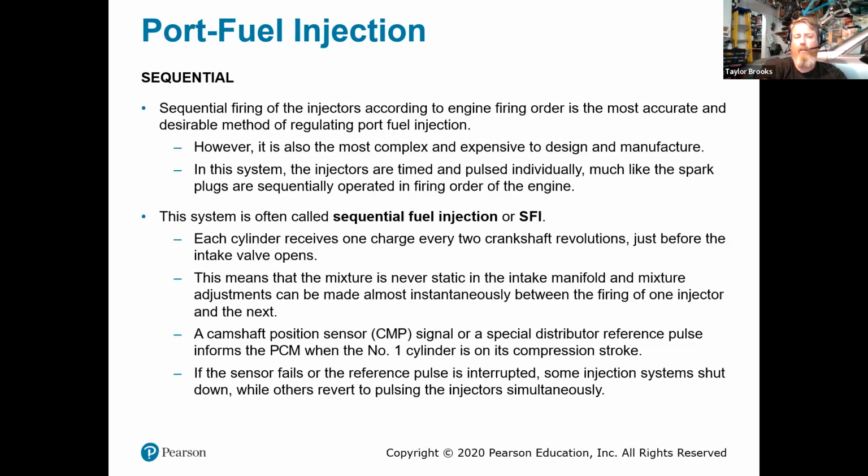Now, sequential fuel injection is the most optimal way to fire the fuel injectors. This is going along with the engine timing. The PCM is going to be paying particular attention to the crankshaft position and the camshaft position, or camshafts position if it's multiple camshafts, and that is going to allow for the maximum amount of performance to be had from these systems.